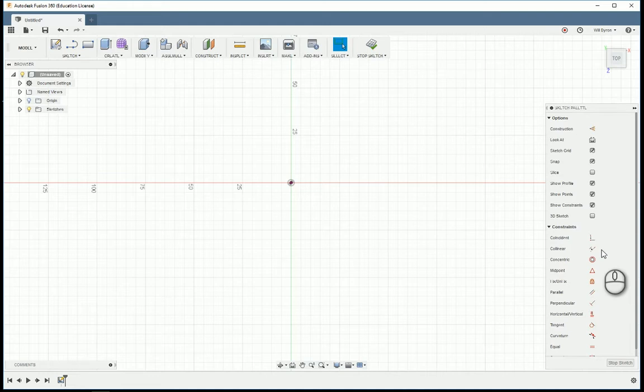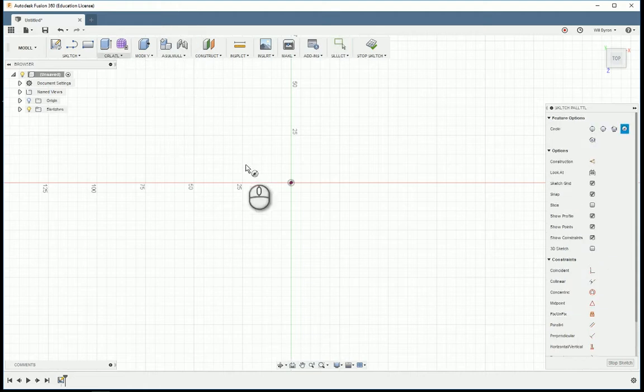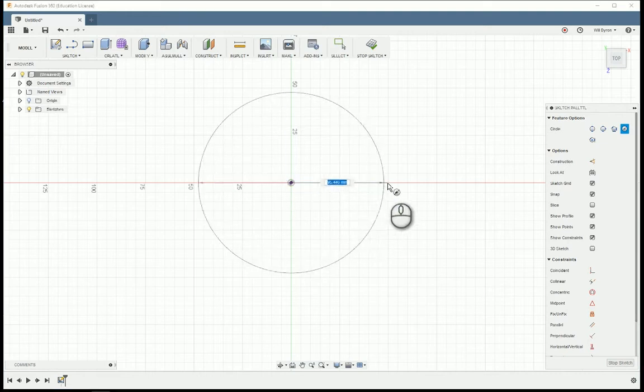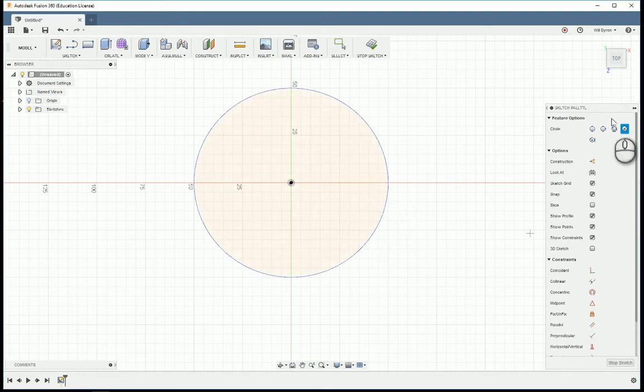And actually a great point is 2 different lines. 2 lines intersect. Digitally, those are just 2 independent lines. If you put a physical constraint on it, I think with the coincident tool, those 2 lines now are stuck together until you physically break that. So if you try and move it, it's going to give you a warning. Do you want to move both of them? Or if you want to scale one individually, it'll also warn you this is constrained to another object. Do you want to break, modify, change? Again, keyboard shortcut here for the circle tool. You can see them next to the individual tools if they exist.